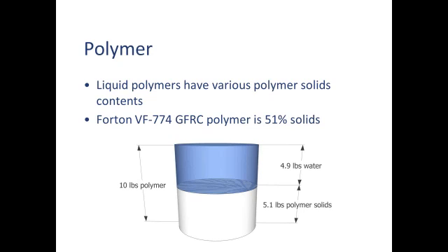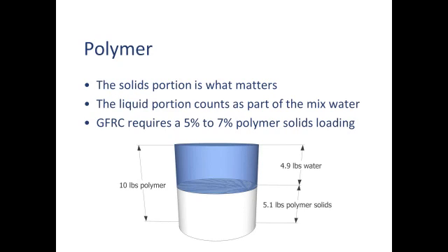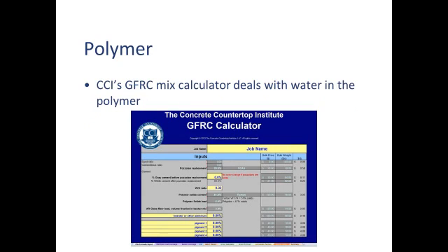Well, when you use polymer in your mix design, that water that's part of the polymer counts as part of your mix water. So you can kind of see how the math will get a little bit challenging to do on your own. I already mentioned all that, so I'm not going to read it again.